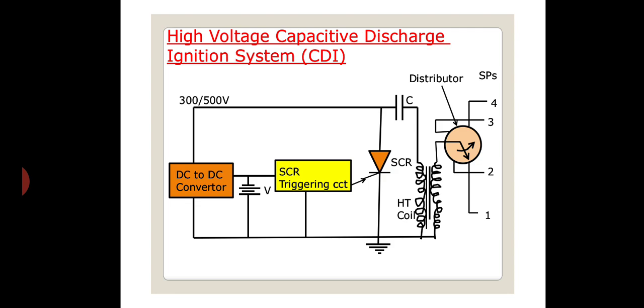Now here you are finding the charging device, which converts the battery voltage to the charging voltage by means of pulse via voltage transformation, the pulse shaping unit and the control unit. The advantage of using this system is that it is insensitive to electronic shunt resulting from spark plug fouling. Because of the fast capacitive discharge, the spark is strong but short, which leads to ignition failure under lean mixture operating conditions. This is the main disadvantage of this CDI system.